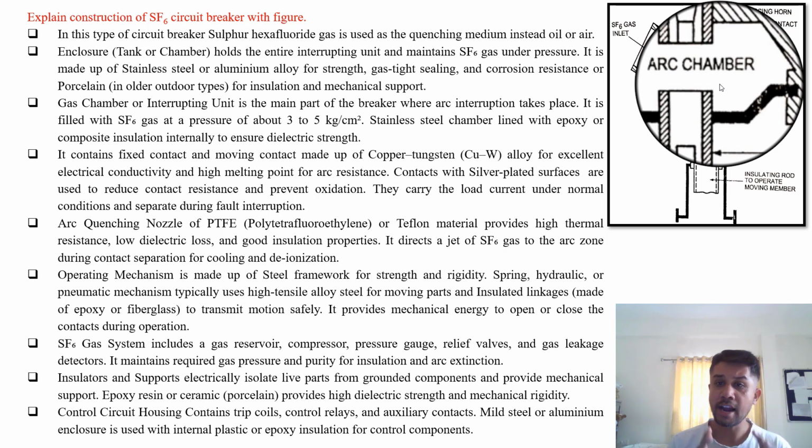Stainless steel chamber lined with epoxy or composite insulation internally to ensure the dielectric strength of the proper assembly. Now it contains the fixed contact and moving contact made up of copper tungsten alloy for excellent electrical conductivity and high melting point for the arc resistance.